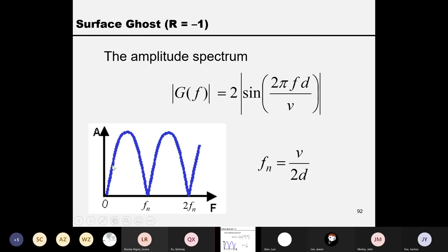That is called bandwidth, frequency bandwidth. We do not measure the bandwidth up to almost zero amplitude because it's hardly possible to find. So that's the standard way. You have the highest amplitude as 1 and half amplitude is here. You measure the width from here to here. That's called the bandwidth.